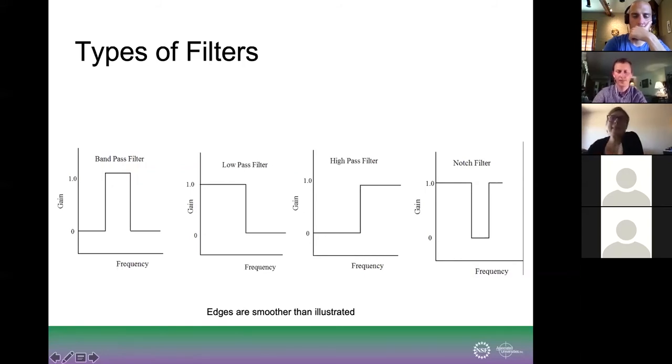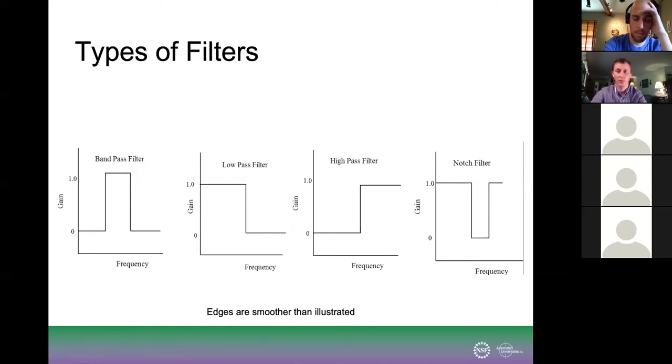We can have a bandpass filter, basically that blocks all the emission outside that range of frequency of interest. Say you care about observing something here and you want to block everything else out. This is very useful for RFI purposes. Like if you have a very noisy radio environment, you'd want to block everything else out except the narrow region in which you care about.